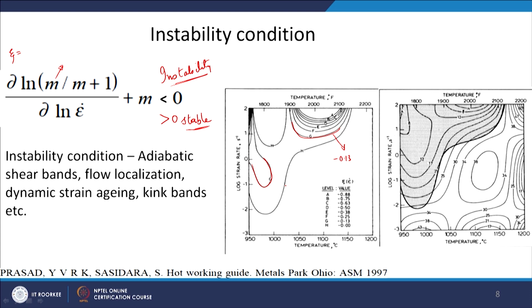Now you can see two things are combined. You have efficiency contours, 38, 34% and so on, and on top of that there is this shaded region, taken from this final contour H, where the instability parameter zeta has a value of 0, and within that everything is negative. So, they have identified this particular region as the unstable region.